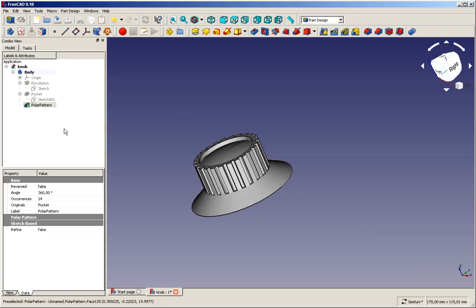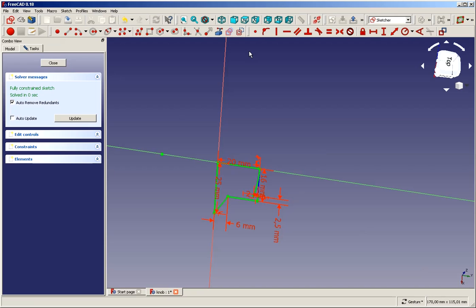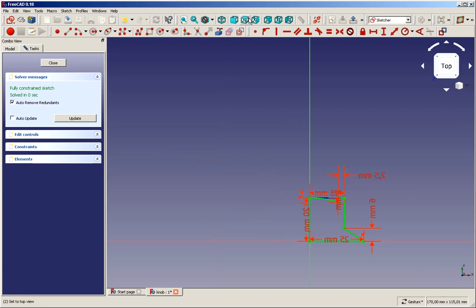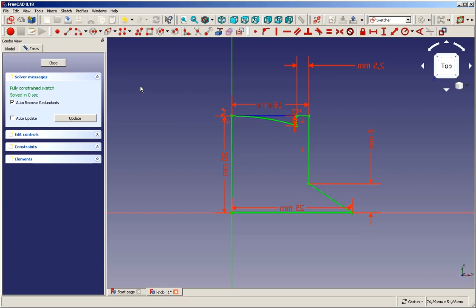So to fix the length of it, we go back into our sketch. We have to move it somewhere, and we look from the bird's eye view, which isn't correct, and that is by principle what I told you. It appears as if that sketch is now on the XY plane, but it isn't, and that is just a visible flaw, but it makes it impossible to select anything here.